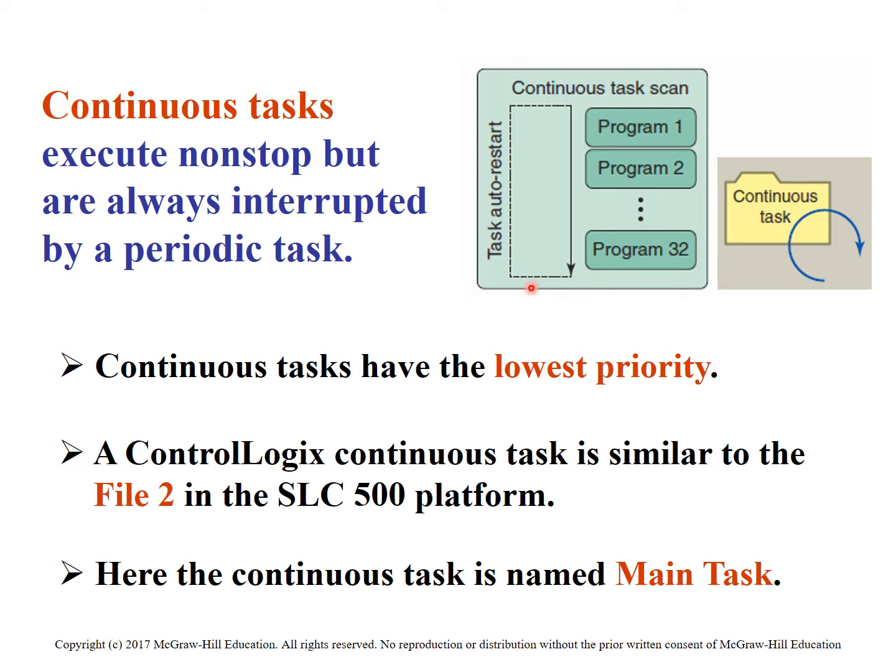So it's a process that stands alone, and remember that term asynchronous. So they asynchronously operate the scan of the program, the scan of the inputs, and the update of the outputs all at the same time.